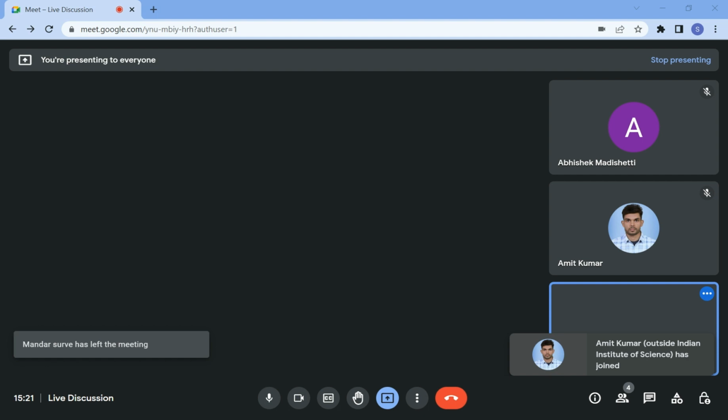But since we located point B, we now know that any point B which makes a constant angle. So as long as I'm not changing the angle with respect to the horizontal plane, although it is visible as 55 in this current condition, if I want to see the true angle, I'm going to rotate it here like this so that this line becomes parallel to the vertical plane, and only then I'll be able to see the true angle.